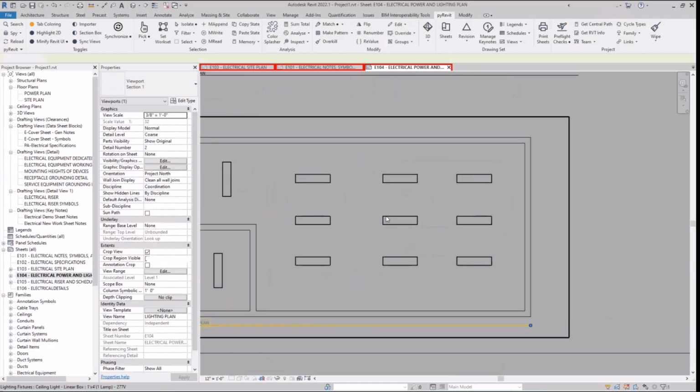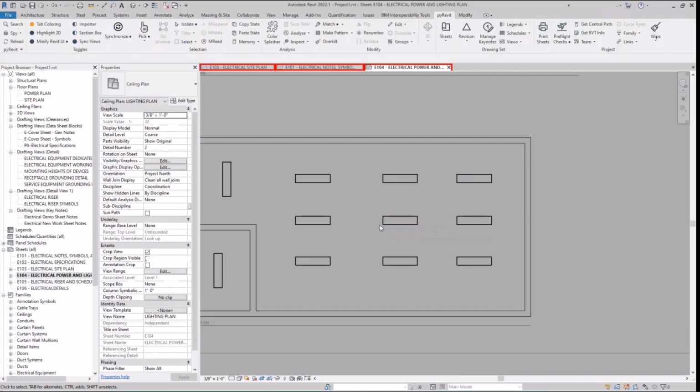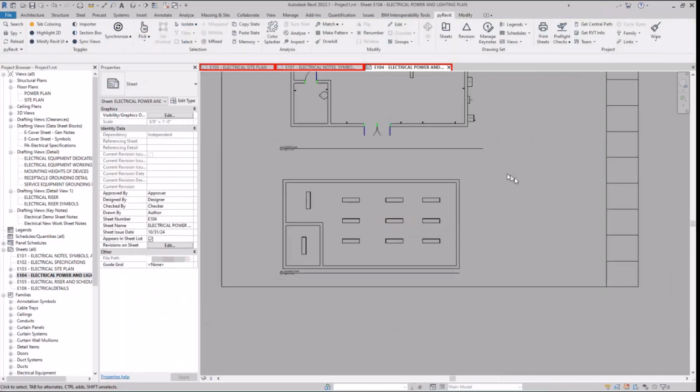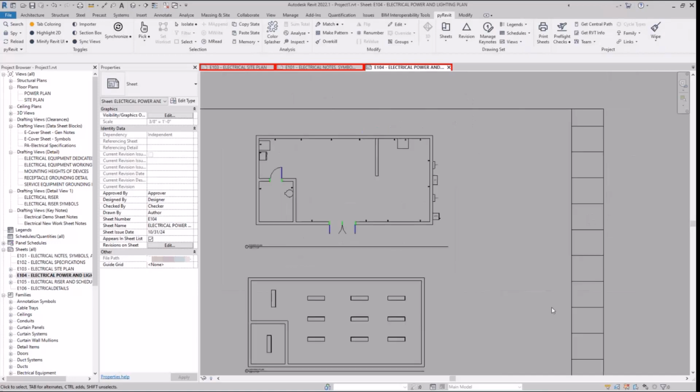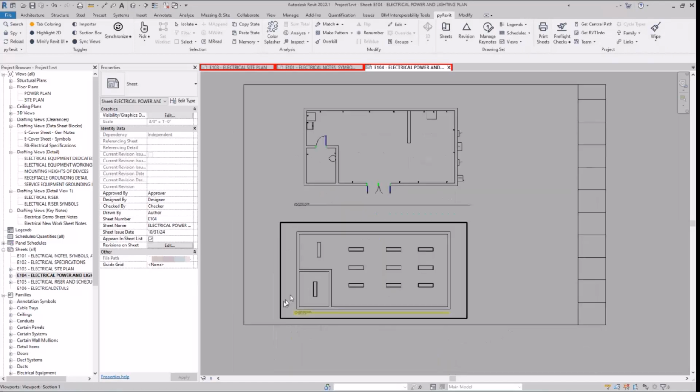The lights we would also label, which I don't have a tag in there for, what type of light fixtures. I would provide a lighting fixture schedule over here that would give the tag, who the manufacturer is, what light this is designed around, what wattage, whether it's LED versus T8 or something, whether it's dimmable, and what the voltage is. That type of information will be in the lighting fixture schedule, which I'm not going to do because it's one light and I'm going to define that somewhere else. And then you would also have the north arrow, whether it's right here or in the corner. Any questions on that?